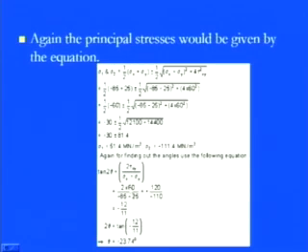So these two, now we can simply put those values to get what exactly the angle is. So again for finding out what the angle is, to get the normal, the oblique plane, or we can say the principal plane, where exactly the principal planes are, or where the shear stress value is 0, we can again go for the same formula which we applied in the previous case, tan 2 theta is equal to 2 times tau xy divided by sigma x minus sigma y. So we need to keep the values of 2 times 60 divided by sigma x, which is minus 85 minus 25.